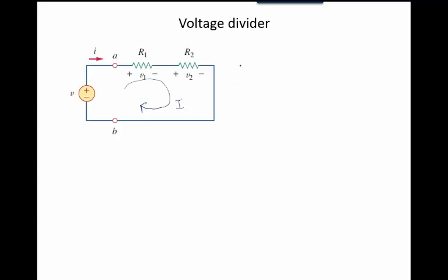This is a DC circuit, so I'll make a capital I. So that's conventional current flow. So in conventional, this is a minus sign first for KVL. So this is a voltage rise, and then all the resistors are voltage drops. This one's already assigned, but I would put plus minus because I have voltage rises equal voltage drops in the circuit. And also power supplied will equal power dissipated in the circuit.